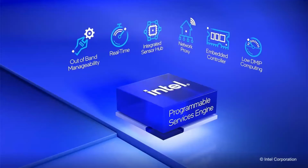This processor also comes with Intel PSE. The Intel Programmable Services Engine is a dedicated offload engine for IoT functions powered by an ARM Cortex-M7 microcontroller. It offers independent computing with low DMIPS and low-speed input-output for IoT applications. In addition to services dedicated to real-time computing and time-sensitive synchronization, the Intel Atom X6000RE and X6000FE series industrial processors support Intel time-coordinated computing and time-sensitive networking.